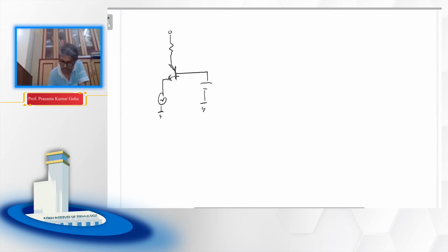You see this DC voltage has an important role to play in the gain that we have discussed before, and this headroom is important. So this is your AV equal to GM RC, and you remember GM is IC over VT, right? ICQ over VT, that is basically your GM.